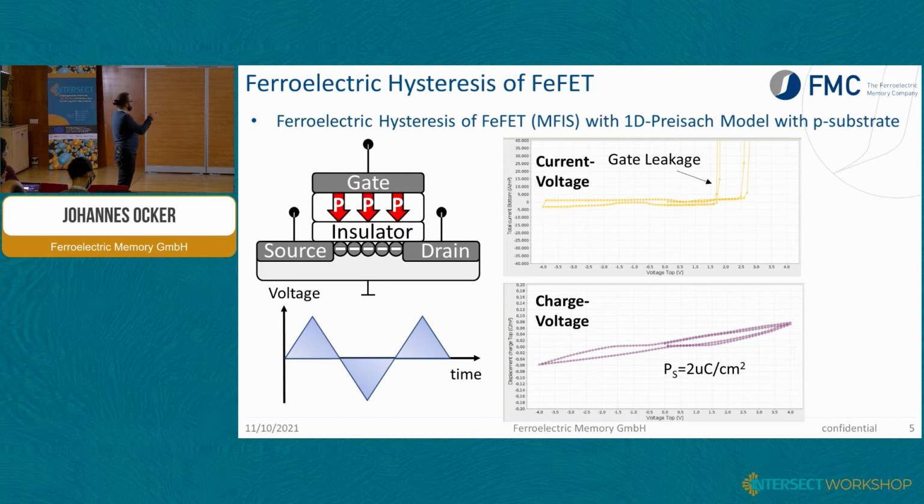that the polarization you can actually stabilize here, and this system is very low. So at 0 volt, the x-axis is the top voltage, you can stabilize only about 2 microcoulomb. And this is because when you sweep up, there is some depolarization field which forms due to the switching of these dipoles, which tries to switch back the dipoles. And this is because of this interlayer here.